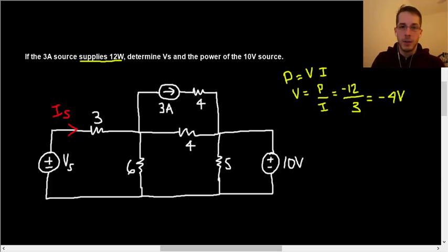Of course, now that voltage coincides with passive sign convention, because that's what power deals with, passive sign convention. So current is entering the positive terminal, because first of all it's going from left to right because of the current source. So then the current must enter the positive terminal, so plus minus, with a value of negative 4 volts. Now that 3 amps is also running through a 4 ohm resistor. Again, following passive sign convention, so plus minus. 4 times 3 is just 12 volts. Again, that's just using Ohm's law.